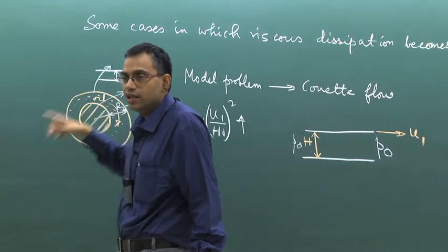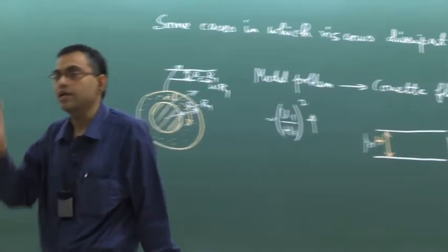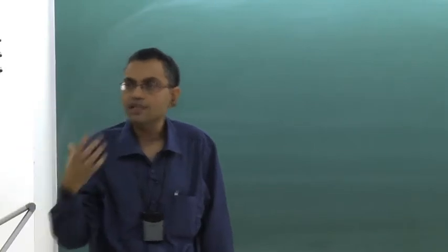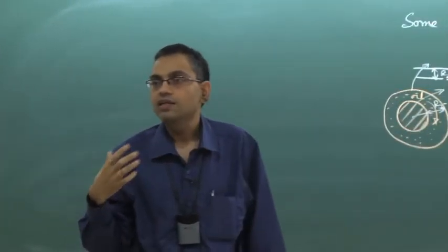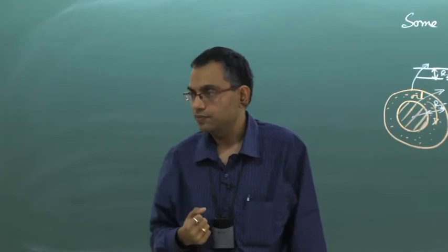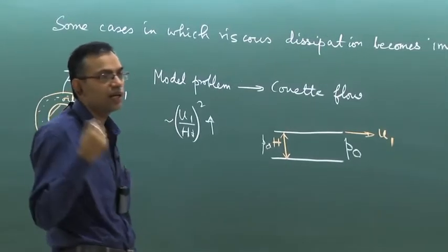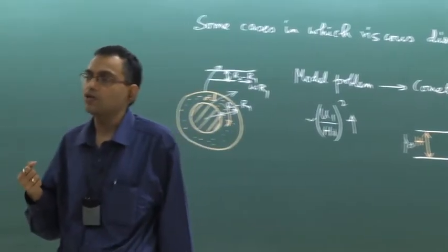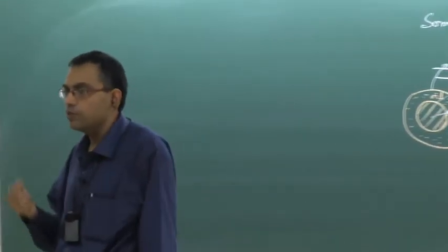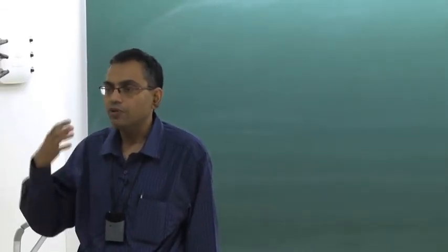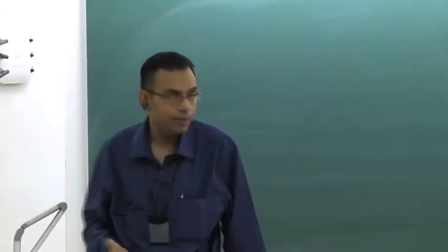When there is a heat source in the oil, the temperature may rise, and that might have several practical consequences in the performance of the bearing. So, it is important to understand what the temperature distribution within this system is. That is our motivation. As we have seen, in convection, when we are interested in the temperature distribution, we first start with the fluid mechanics analysis, because we need to get the velocity field, and we will use the velocity field to get the temperature field.